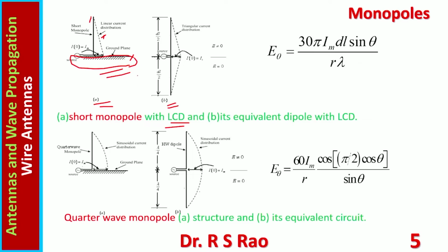It means both give the same radiation, with one difference, of course. Structure in B gives radiation in all directions, whereas the structure in A gives radiation only into the upper hemispherical region. Hence the point is B is equivalent to A only for finding radiation field intensity in the upper hemispherical region.